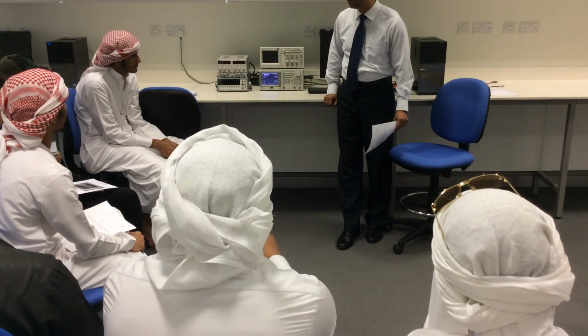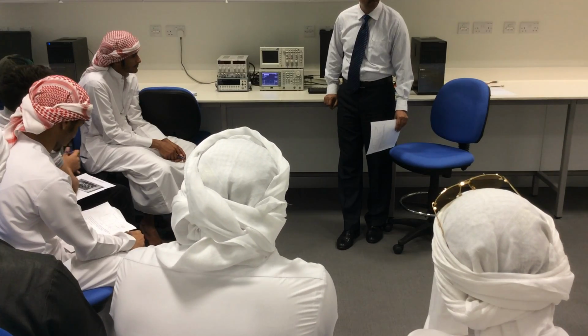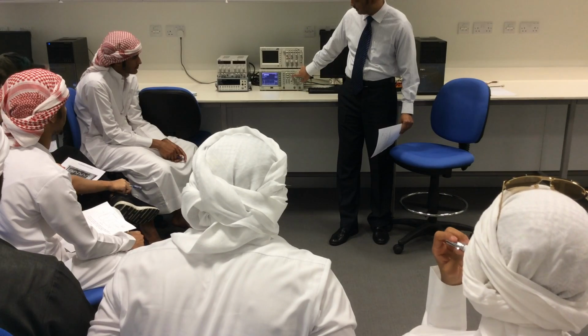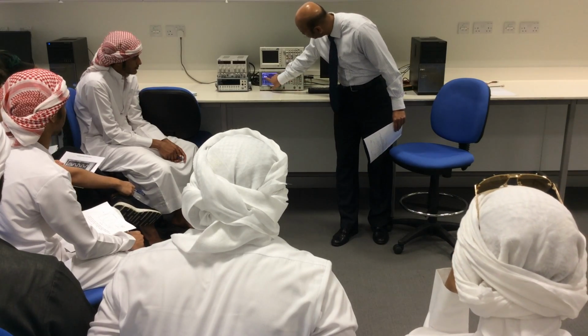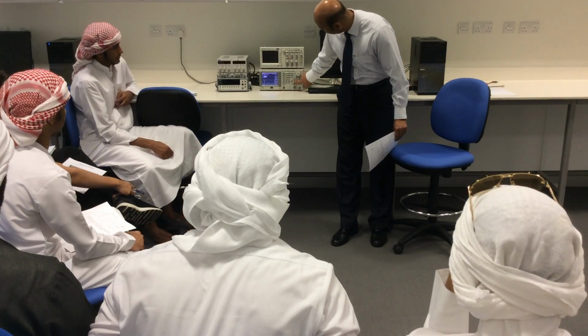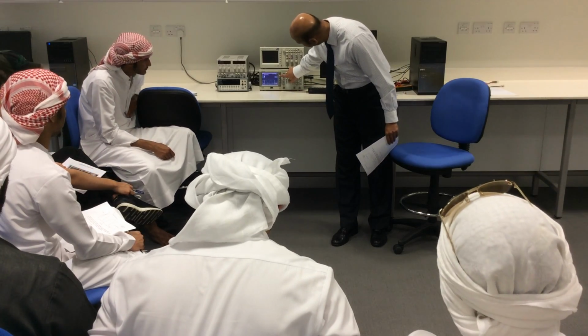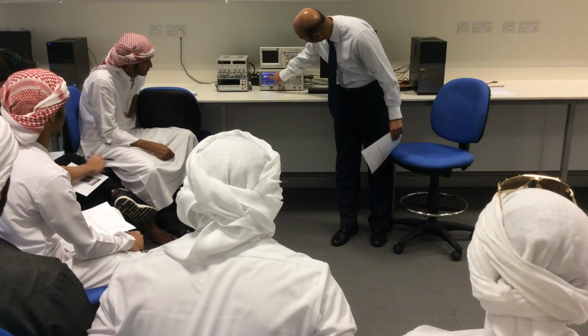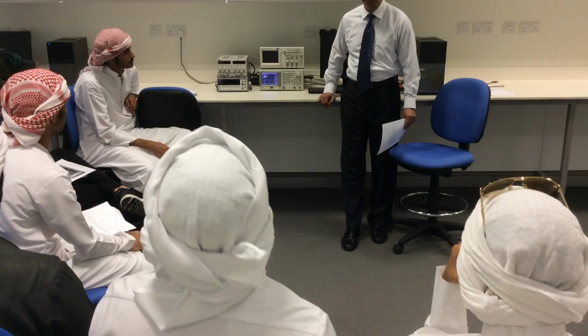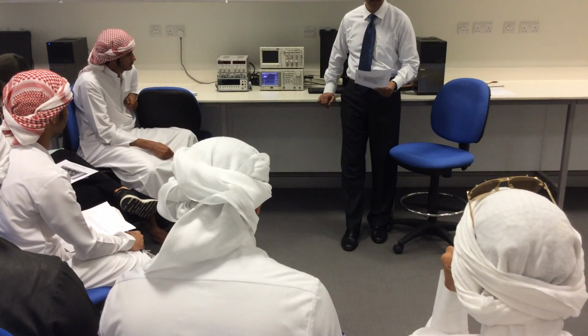The second thing we want to set is the peak-to-peak voltage. For that, you will see this amplitude. You press this, and now it is on the amplitude. How much do you want? 1 volt. It is already 1 volt, but I'll type 1, and here you press VPP, and this is 1 volt VPP.